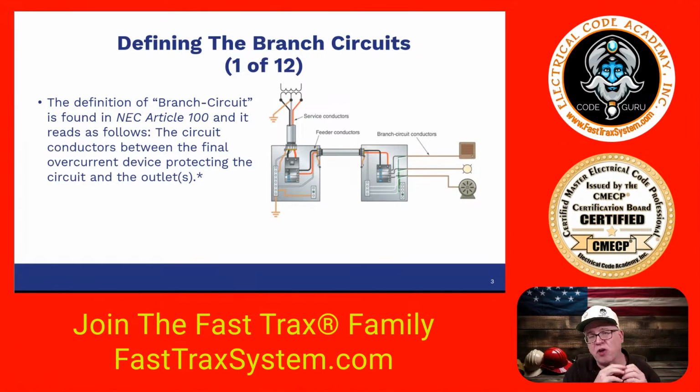It's from the last overcurrent protection to the outlet. Again, whether it's cord and plug connected or hardwired there. That is what an outlet is, and that's what a branch circuit is. It's between the last overcurrent protection and the outlets, okay? So we're protecting these conductors with this overcurrent protective device right here, and it is the final overcurrent protective device.